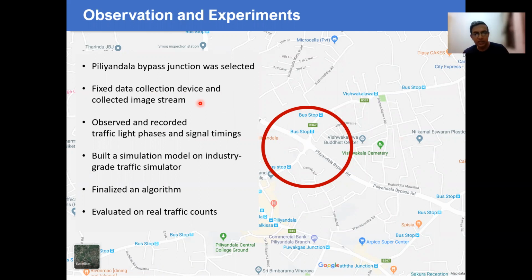We did some simulation on SUMO, and in fact, in SUMO it's difficult to adjust timing directly. So we had to improve SUMO so that we can implement adaptive traffic control on it. It's originally a simulator, but not a control platform. So we improved it a little so that we can do the timing and then put it back on the simulator and see how it happens. This is the junction we did the simulation on.